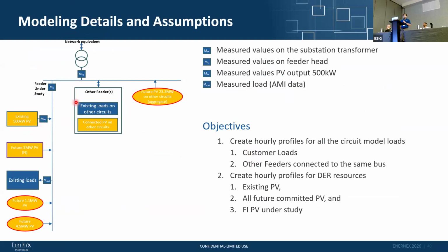Let me go back up. We had to model the substation transformer. Again, some of the feeder. So there's other feeders along that are connected to the same substation. So we looked at those as kind of aggregate loads, as well as aggregate all the PVs. So all the other feeders on this bus were kind of modeled together. And then the feeder that had the FI PV here, we kind of looked at separately.